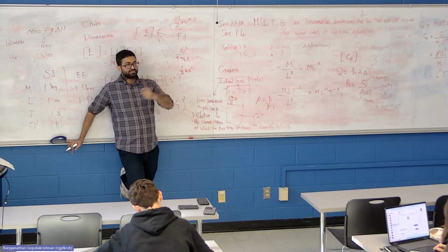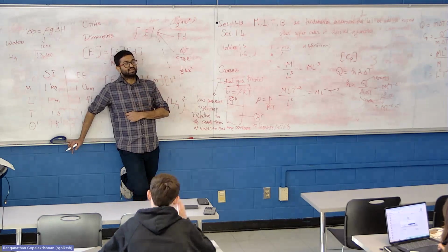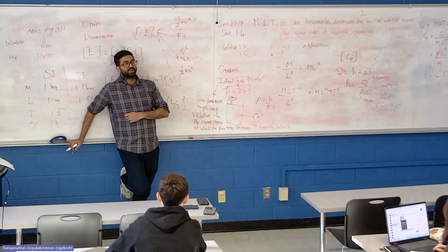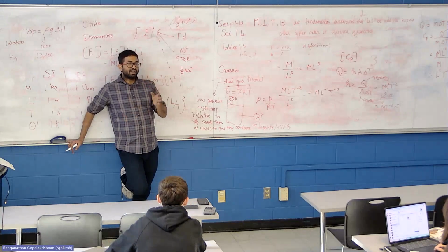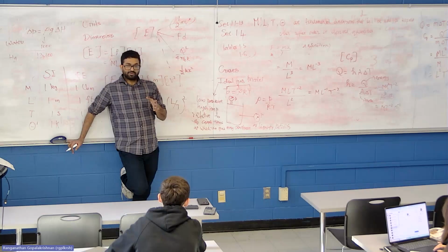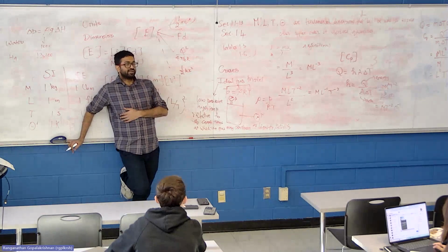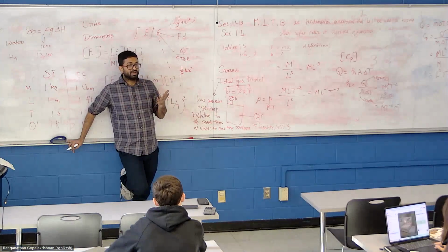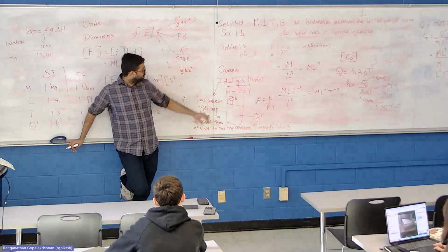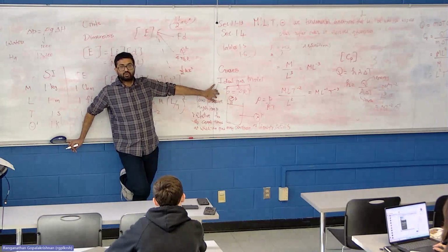Yeah, it depends where you are. Let's say I am at 102 degrees Celsius and 1 atmosphere pressure. No, because I'm kind of on the line of condensation. If I drop a couple of degrees, it will start condensing. But if I have superheated steam, at, let's say, 400 degrees Celsius and 1 atmosphere pressure, this is actually a pretty good approximation to describe the state of that superheated steam.